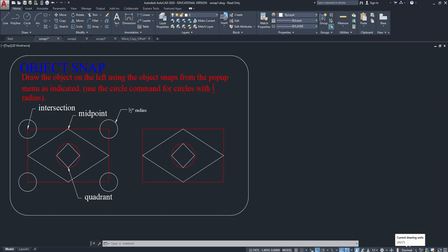In this case, we're going to be using decimal in this drawing, but I can also change this to architectural, right? So let's do that for a second. And I want to talk a little bit about inputting dimensions in AutoCAD. I'm going to click on the line tool. I'm going to object snap to the endpoint here. Click. I'm going to move in the direction I want to go, and you see that my ortho's on, so I'm getting a perfectly straight line. Near my cursor, you see a dimension popping up, and it says 0 foot 5 3/16 of an inch.